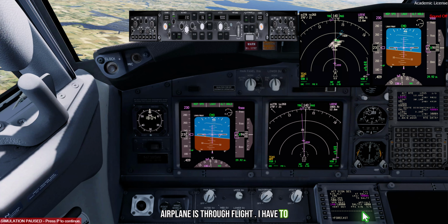I have to at least match that vertical bearing, because a vertical bearing is the calculation by the computer to get to that waypoint, 4,000 or above, at this ground speed. Don't be confused on that. It's not the indicated airspeed, it's the ground speed. Now, we're going to talk about some other aspects of this as we start to fly the approach, but I really want to start to emphasize this.